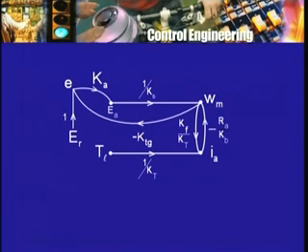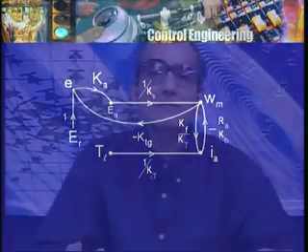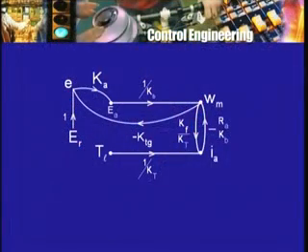One should interpret terms or coefficients that appear on the graph and the various signals. It's not good enough to just do things mechanically, because only then can one understand what's going on and also notice if one has made any mistakes. So this path from omega m to Ia through Kf by Kt once again is because Kf omega m is the frictional torque, that divided by Kt is a part of the armature current that is required. The other part of the armature current is required to produce the load torque, and therefore TL divided by Kt, and that's the summation at Ia.